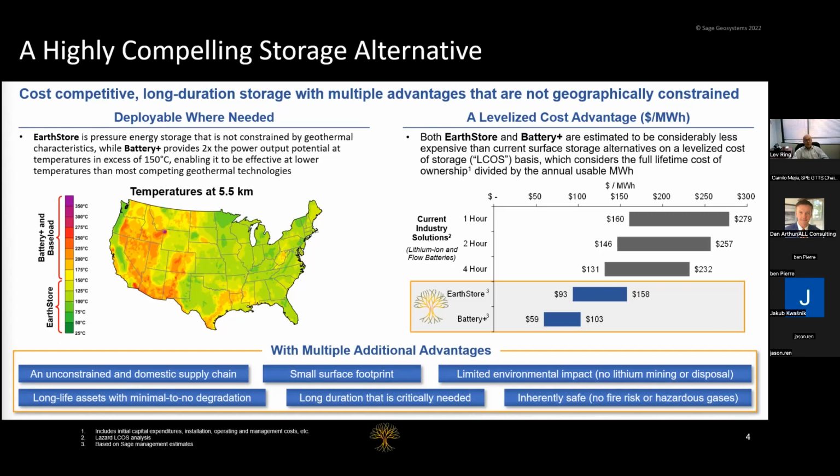But from a physical standpoint, there is not much difference between pumping up and pumping down. The highest pump storage is built in Chile. It's about 1 kilometer or 3,000 feet high. As you know, we can easily drill to 15,000 feet, and that is going to be like 5 times higher energy density, or lower footprint, than pump storage. And it can be implemented on any scale from 3 megawatts to 100 megawatts. Very scalable and very dispatchable.